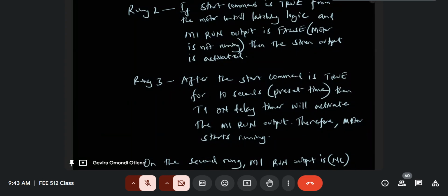But I told you, I want us to make use of something else. I don't want to do off delay timer, because it's just working in the opposite way of the on delay timer. But I want to make use of the on off timer. Okay. We want to have a flasher circuit, meaning we want to have an output that has lights flash on and off. So you have two sequences of both on and off.